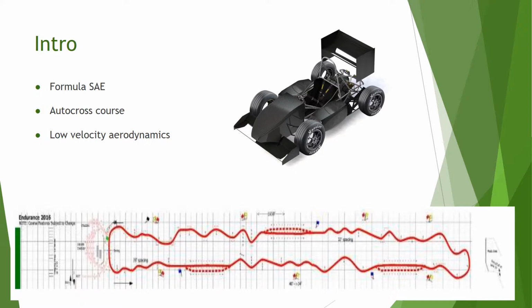An aspect of a well-performing car is having a front and rear wing that create lots of negative lift, otherwise known as downforce, at the cost of creating additional drag. This downforce ultimately creates more traction for the vehicle in turns and increases cornering speeds, therefore decreasing lap times.